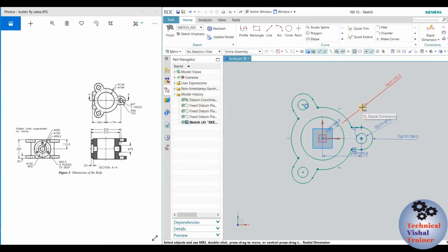So I am able to get this outer structure of the sketch, and the sketch is again fully constrained. I have given the required dimensions and required geometrical constraints to make the profile fully constrained. And now you see, if you start with any point, there is only one path to complete it as a closed sketch. There are not two paths. In the previous case there was an arc, so if I look at this, there would be a path like this and a path like this. We don't want to create that as a path, so we are going to trim the inside portion.